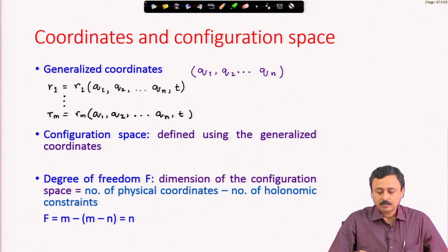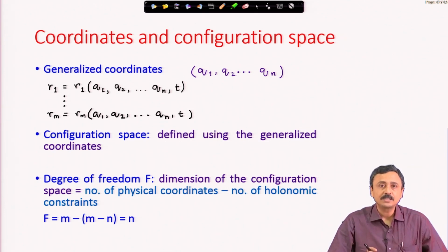But holonomic constraints do reduce the degree of freedom. Like in the coin example, the z coordinate of the center of mass, zg, was related to the tilt of the coin phi, and that helped us remove zg from the list of coordinates and get a reduced set, and it had 5 degrees of freedom.